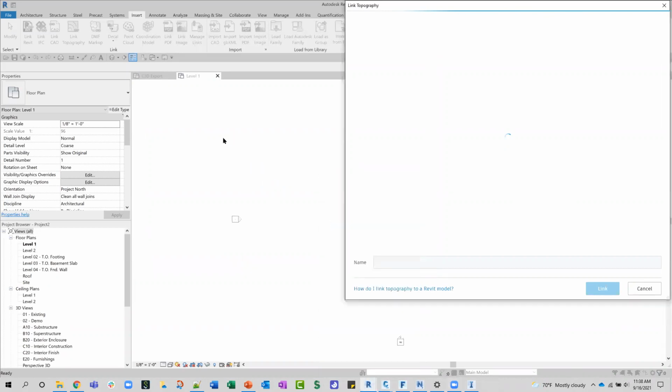All right. So what you would see under the Manage tab, you go to your Site and Location. After you acquire the coordinates of that linked topography, it's going to change from that typical dialog, typical interface, and it's going to show Connecticut NAD 83. So it knows exactly, it's got that same coordinate system. It's reading the same information.